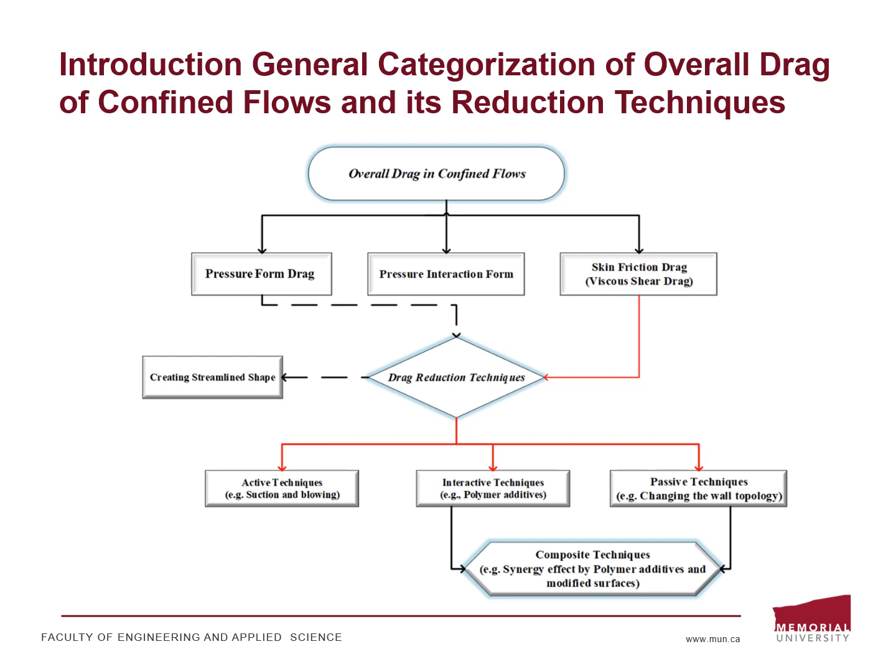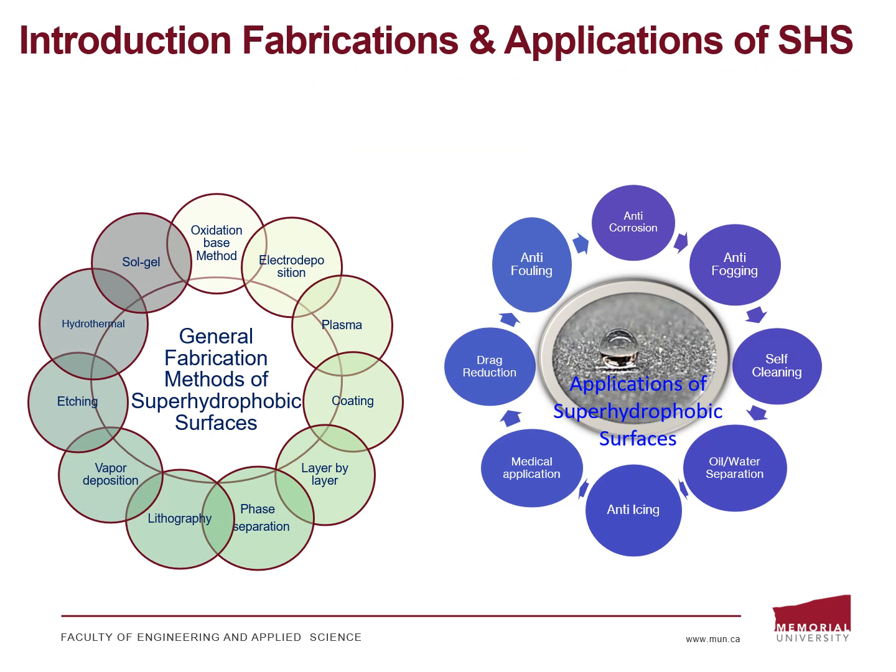And the third one is the passive technique, which depends on changing the wall topology to a superhydrophobic surface. There is another composite technique, which is a hybrid synergy effect of polymer additives and surface modification. But our focus will be on the passive technique using superhydrophobic surfaces.